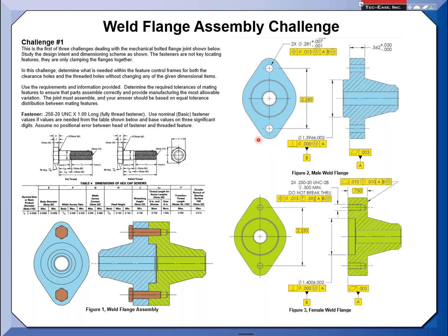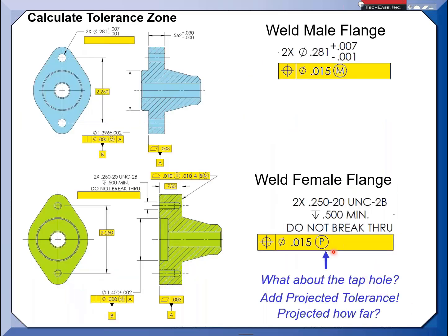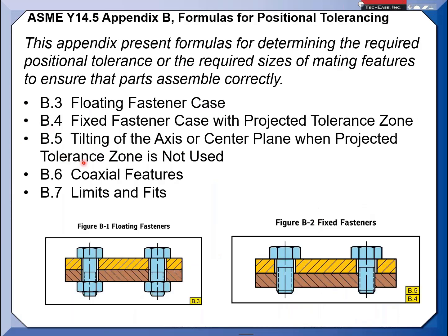Hi, Ed. I have a question. Do you have time for that? Sure. So if I don't use the projected tolerance, I understood that I should restrict the geometric tolerance to 0.015 with a formula. Could you please explain how that works? So in this case we're dealing with this projected tolerance zone? Yeah, so if I don't use the projected tolerance zone, then I need to constrain or restrict my geometric tolerance, 0.015, a little tighter to bring this bolt into the perfect position. And if I understood correctly, you told me I need to use a formula for that. Could you please explain that?